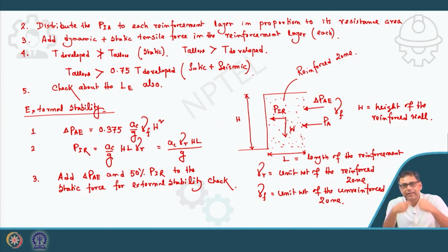And then you add them to the static forces, and then do the external stability checks, like the factor of safety for overturning, sliding, no tension and the bearing capacity. So you do the check.